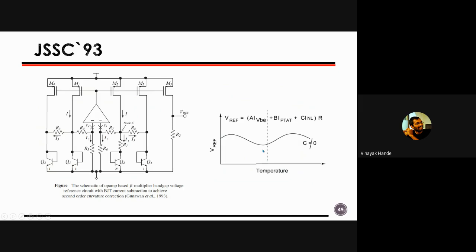It is kind of folding back that upper peak, so you can improve your accuracy at least by a factor of half or something. It depends, right? As I said, when you are using a 16-bit, 18-bit or 20-bit ADC, then people go for a higher order corrected voltage reference, if you are using the voltage reference for generating the reference.